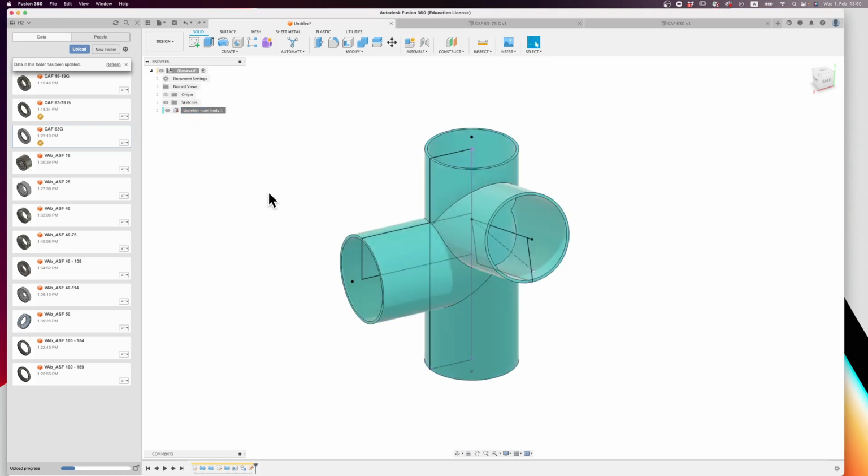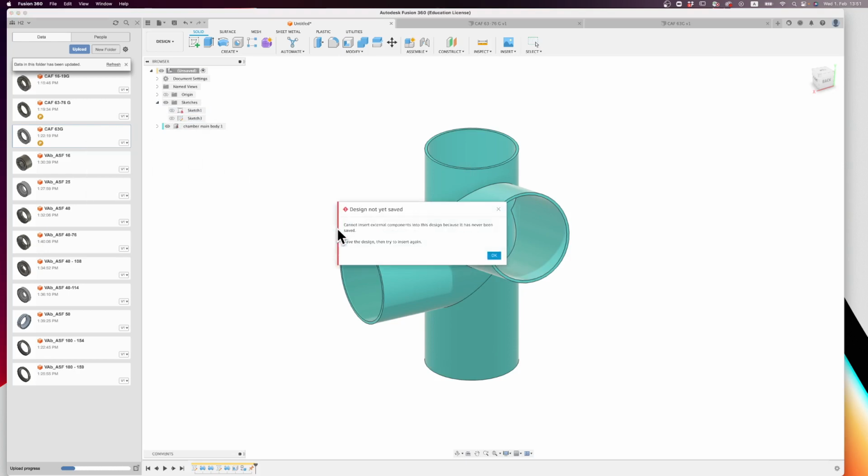that component. And there always needs to be one grounded component in your assembly, because this is the reference everything references to. And right now, we're not going to need these sketches anymore, so I can switch off the sketches. Because the next thing we're going to do is insert into this design